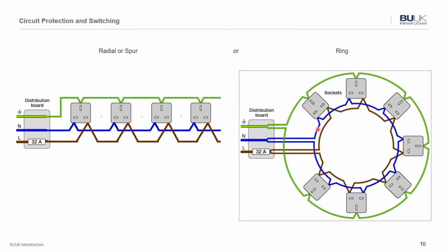The other advantage you have with a ring network is that because current can flow both down this route and this route to get to this location, we've effectively got two parallel conductors running side by side, and when we have two conductors or circuits in parallel, the resistance is reduced significantly. So we can end up with a lot smaller cables to carry the same amount of current.